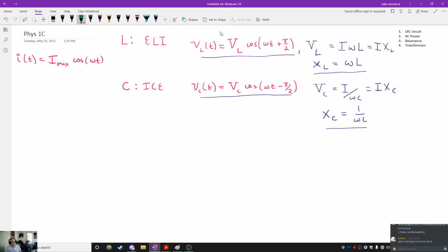We know that inductors respond to high frequency current because that's what an inductor does. It doesn't like changes in current, right? So if we write an inductance times a frequency, that gives us a number that represents how much the inductor resists, not really just changes in current, but also just resists current in a way. Because now that you have the quantity, it acts basically just like a resistor. Again, compare both of these two equations to the equation that we're relating them to, which is V is equal to I times R.